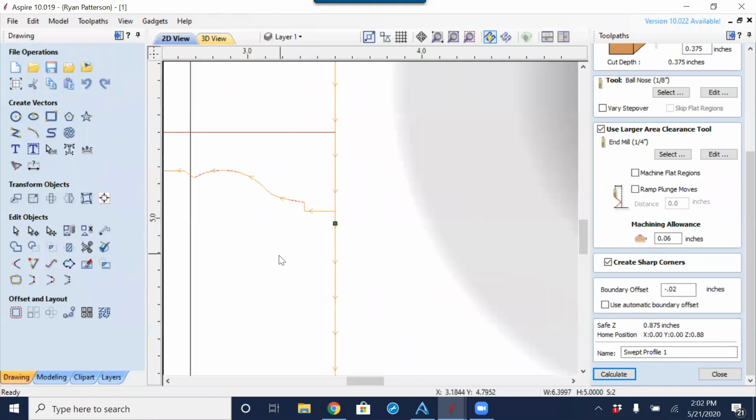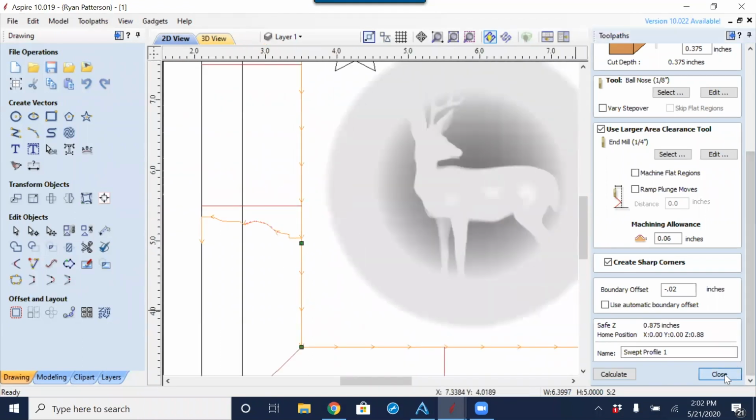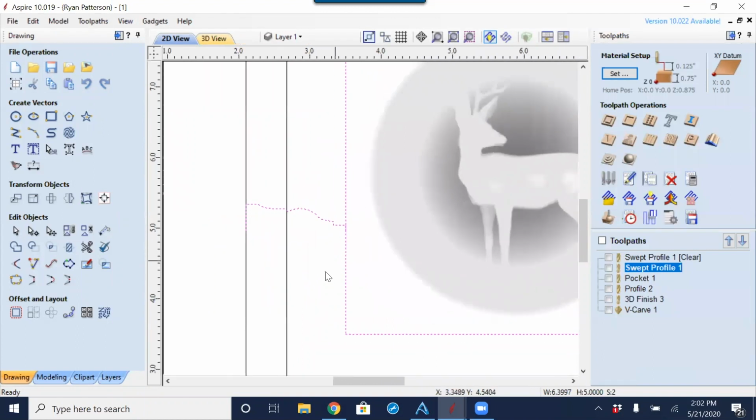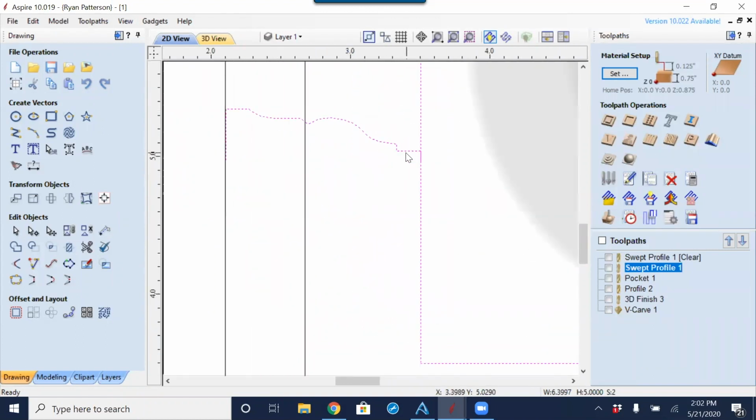And to speed things up, you may want to think about the profiled shape as well, and not even have this section be used. So you might trim away some of the profiled shape to not include this flat section, because even though it's not that big around there, there are several passes that a 1/8 inch bit is going to make to clear that flat.